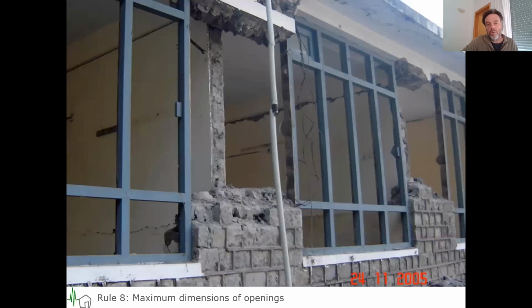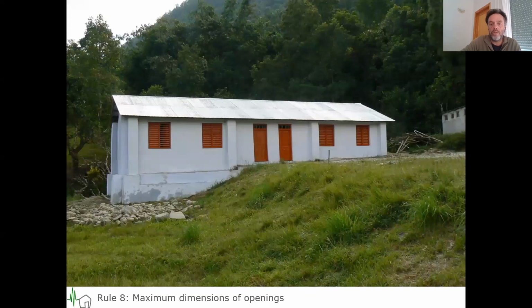These are examples of where it went completely wrong. This little bit of masonry here was supposed to deal with the total earthquake forces, and it literally exploded. It just couldn't handle all that force. Here we see too much opening versus too little masonry panel that should resist the earthquake force.